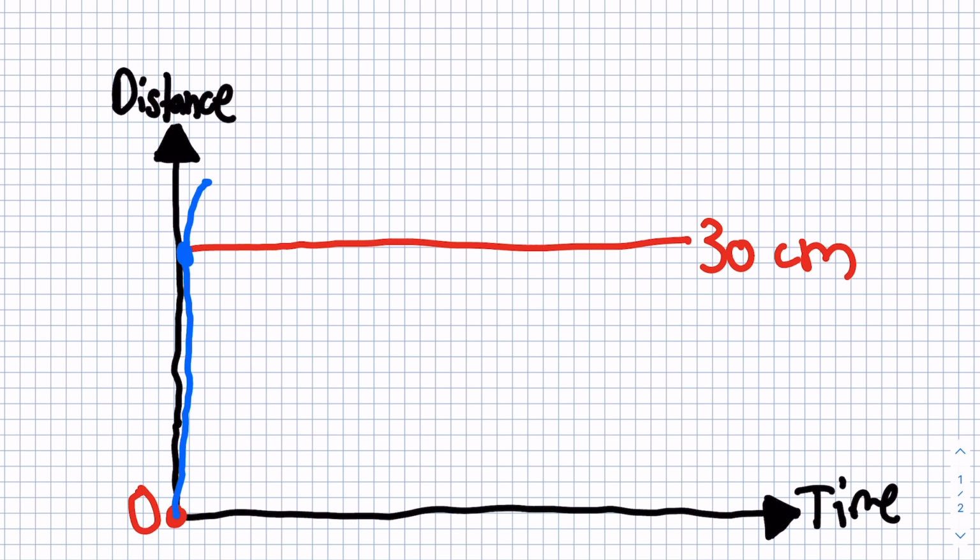And now remember, whenever we apply power, there will always be momentum. So, once we overshoot, we'll try and fix it, but then we'll undershoot because of that momentum. Then we'll overshoot again, undershoot, and so on. And we would have many oscillations. And we don't want this as it takes longer to get to our desired position.